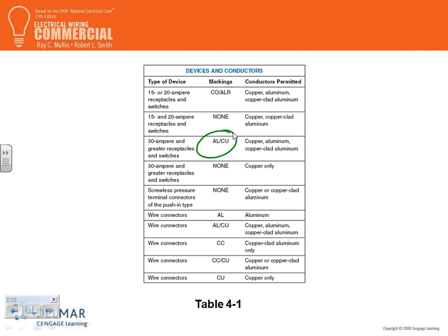I've seen it. Yeah, yeah. But it's for torquing and for corrosion, you say. But I believe the lugs themselves have to be rated as either you bring this or that, not both. If your lug wire connector says CU, look at what they're saying. If it says CU, what do you need to bring here? You need to bring CU only, copper only.